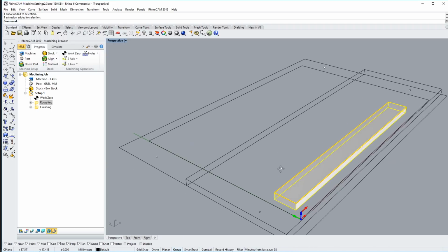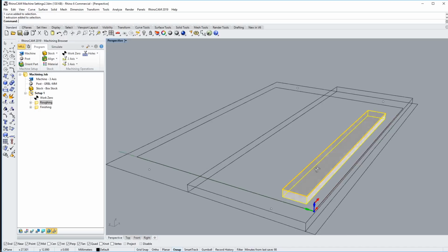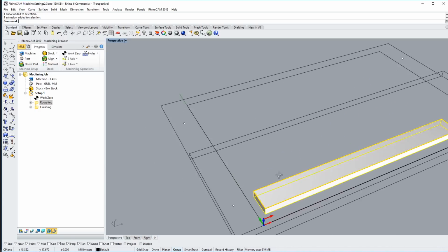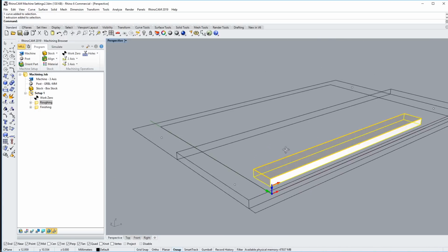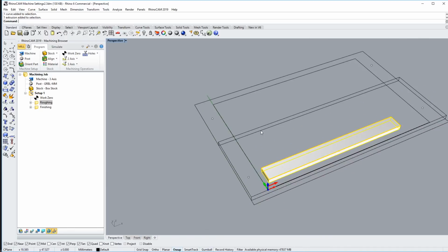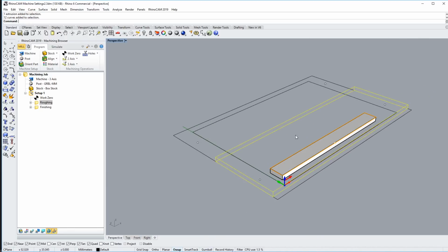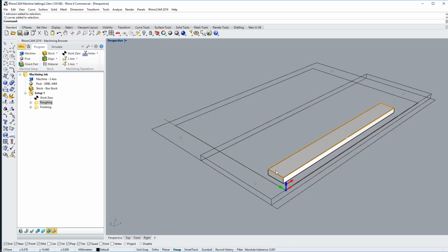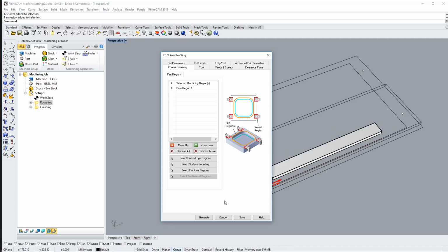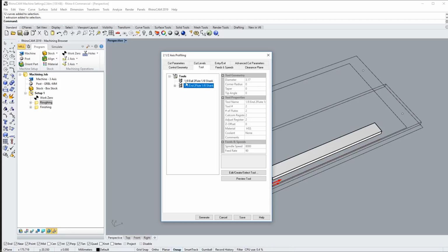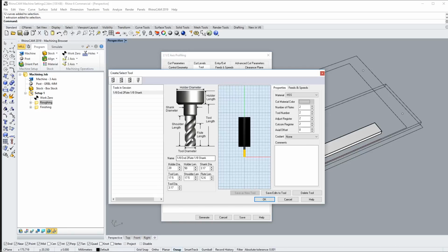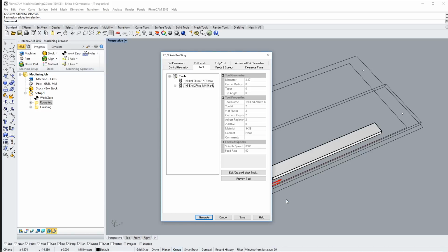So within those 2 rectangles, you can see I've drawn in this box, and that is meant to be my first test cut. So I'm cutting it out of this stock. That's what those lines are, to represent the stock material, just the chunk of aluminum that I'm going to be cutting this out of. So let me show you guys some of the options available in a real toolpath generating program. Starting with the tool, you can declare all the variables for the tool and the holder so that you can model it so you get clearance so you don't collide with your stock.